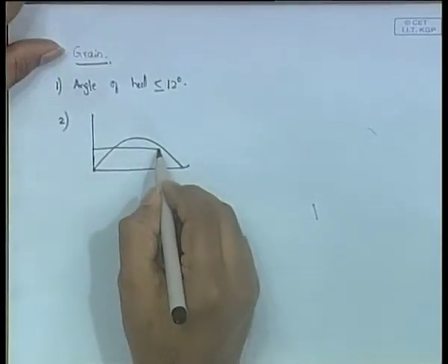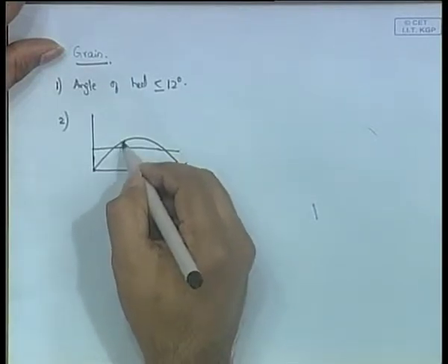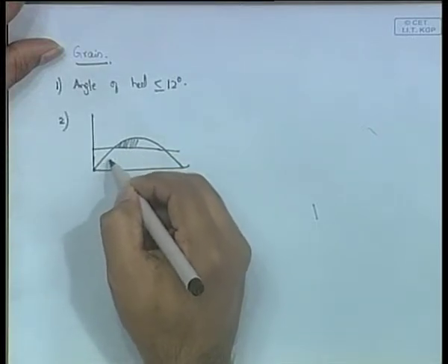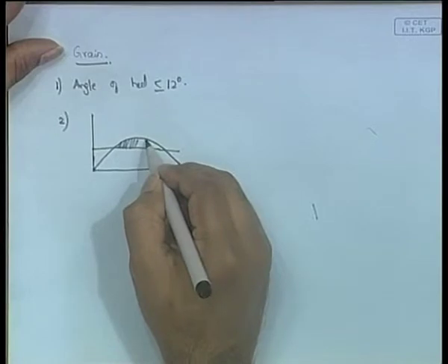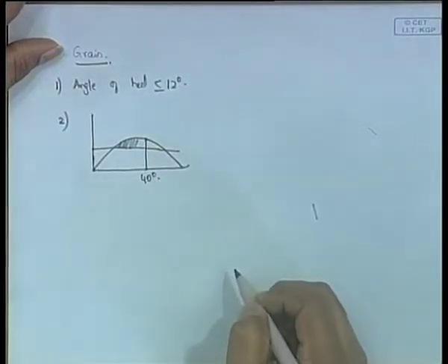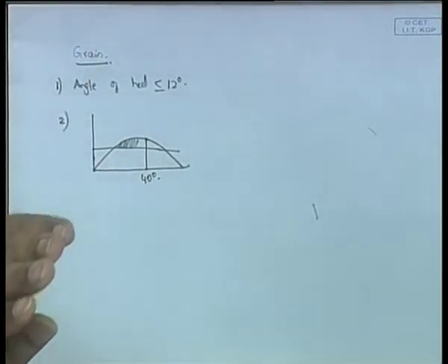The rule says that the area between the righting arm curve and the heeling arm curve, which is this area, up to an angle of 40 degrees or an angle of flooding if it occurs before. Angle of flooding means because of the heeling, some hole that was on the freeboard has now come into the water, as a result of which water is entering. That is called the angle of flooding.